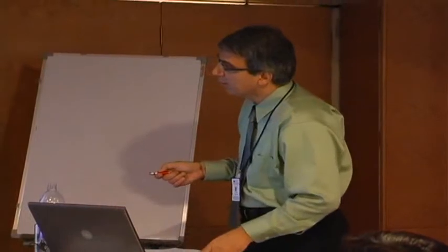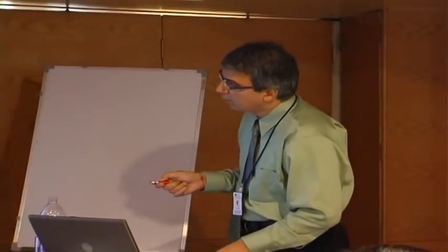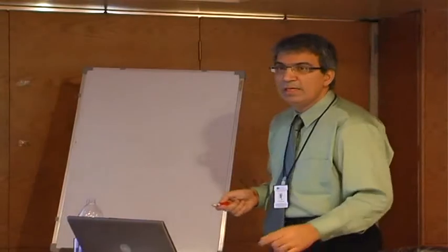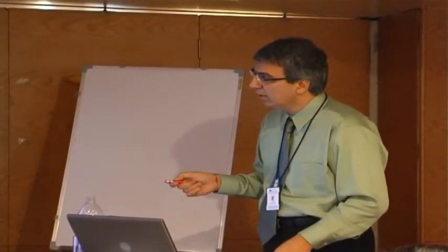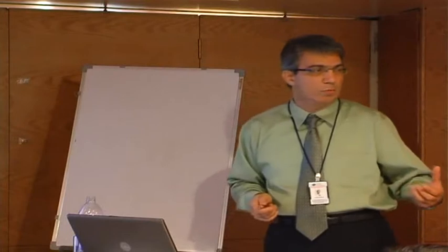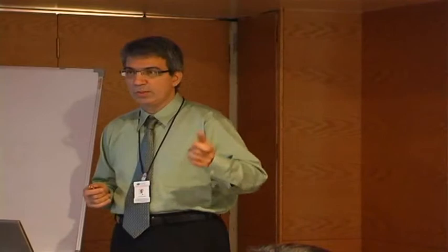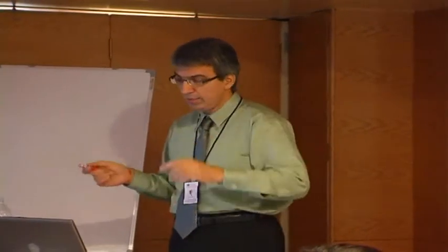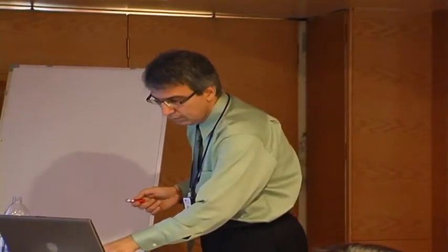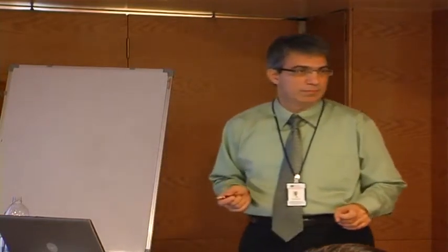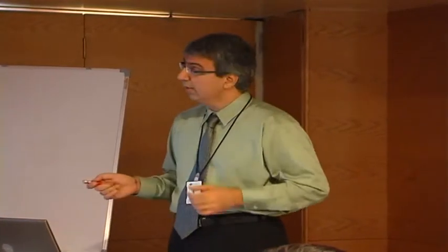So right here in the middle, when you transition from one phase to the second phase, there's a dip. And the more inductive your motor is, the bigger the dip in the current you're going to have. And that's where, if you have this kind of strategy, it will not work for highly inductive motors, because these diodes will eat you up. The output will have a lot of ripple and a tremendous amount of losses because of reverse recovery of these diodes.